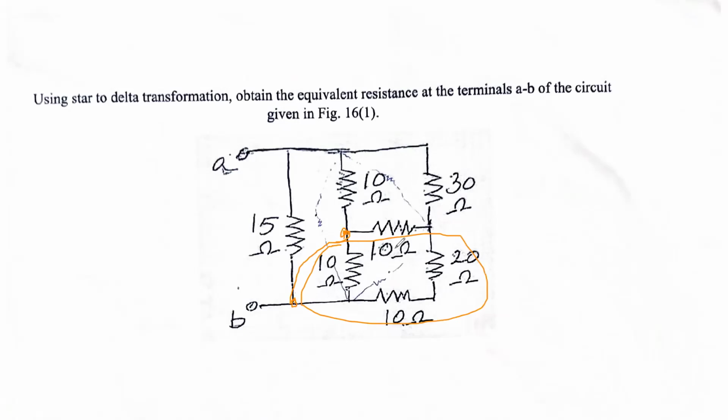Because it's here two stages there, definitely something will be there. So you need to go for the correct star delta or delta to star, whichever possibility is there, convert it, and further proceed and solve the circuit.